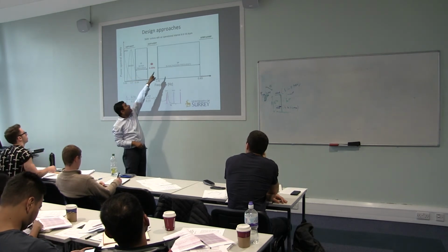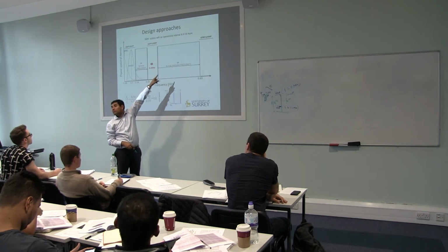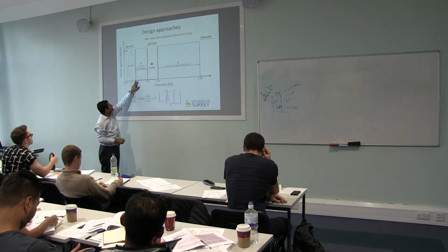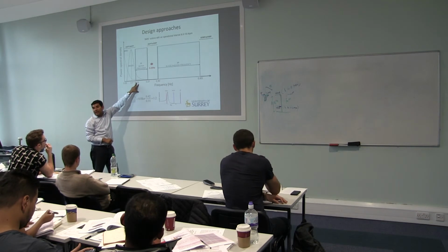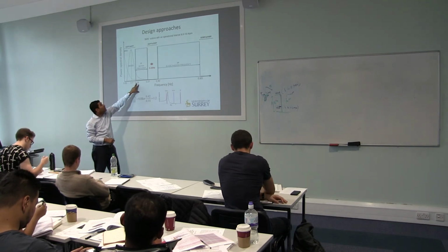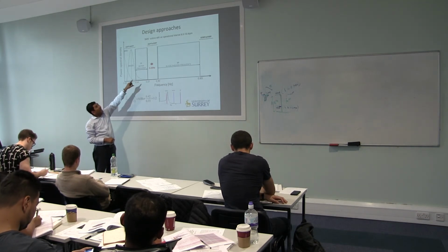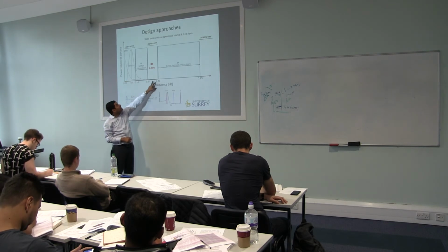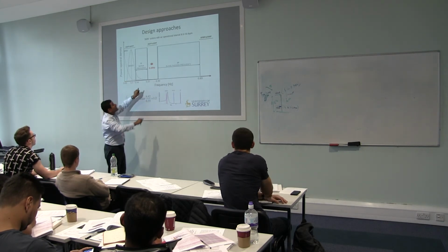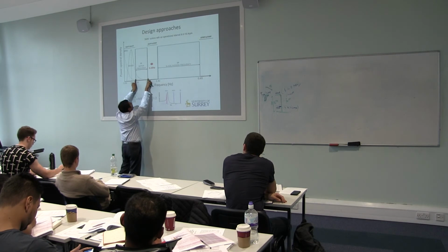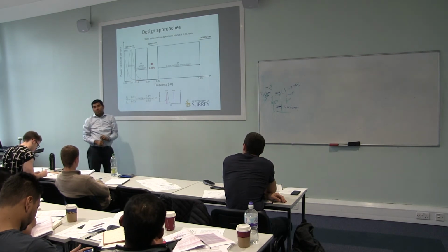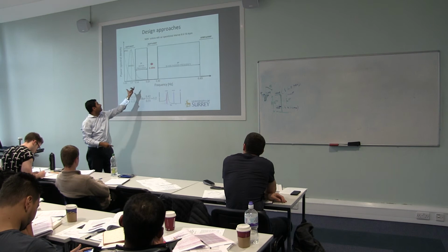Look at the interval, 8.6 to 18.4 RPM. 8.6 divided by 60 will give you 0.14, and 18.4 divided by 60 will give you 0.31. So this spectrum is for a 3 megawatt turbine, but for an 8 megawatt turbine, you have a different spectrum.